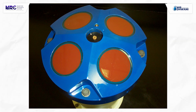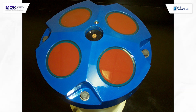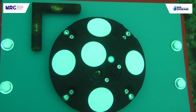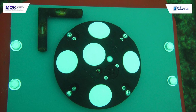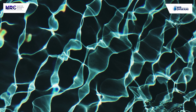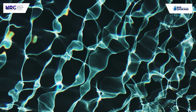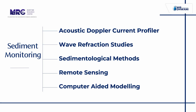For example, an acoustic Doppler current profiler is an instrument which can measure both the quantities of current velocity and sediment concentration from a vessel. The direction of the sediment transport can be detected using geomorphic indicators or by tracking movement of artificial tracers. Computer-aided wave refraction studies can determine the places of wave convergence and divergence, which provide a quantitative measurement of the littoral drift and the direction in the local and regional areas.